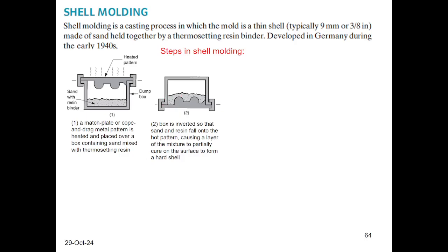Since the pattern is hot, the sand particles together with the binder are cured, and cover the pattern well, forming a shell.